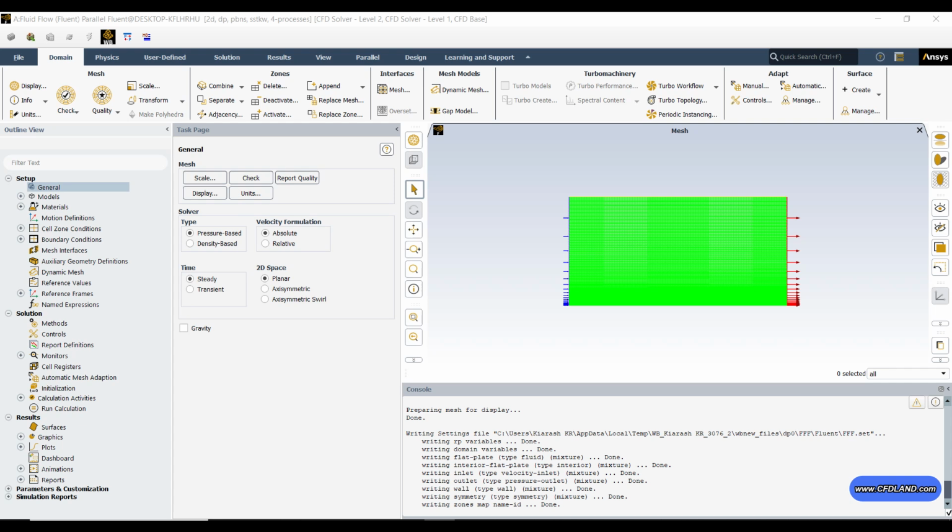The distinction between steady and transient time modes is fundamental. These modes describe how a system's properties change over time, which in turn affects the form of the governing equations, including the Navier-Stokes equations or the energy equation. For this simulation, we already know that a steady state condition is governed, so we keep the steady state time mode, in which the variables, including velocity, temperature, pressure, and many other variables, do not change with time. Now it's time to define the turbulence model.